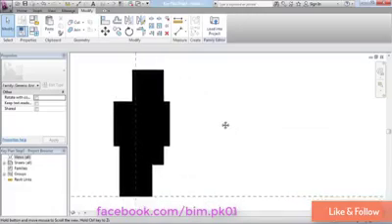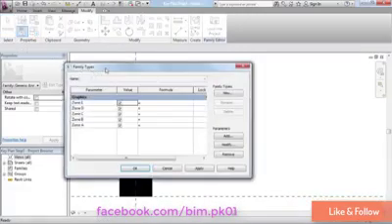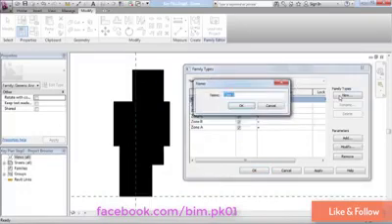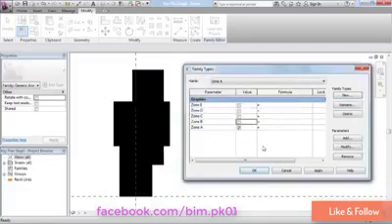And I'm just going to slide it over a little bit here so that when I open up the Family Types dialog, I give myself some room so we can see what's going on in the background. You can see here in the graphics group, I have the 5 visibility parameters that we set up in the previous movie. And there's really two approaches we can take to this. We could simply create family types, call it zone A, and uncheck all the others and click apply. And in doing that, that's a zone A, and then repeat zone B, zone D, and so on. And that certainly is effective, and we could finish up in just a few minutes, and it would, for the most part, work just fine.